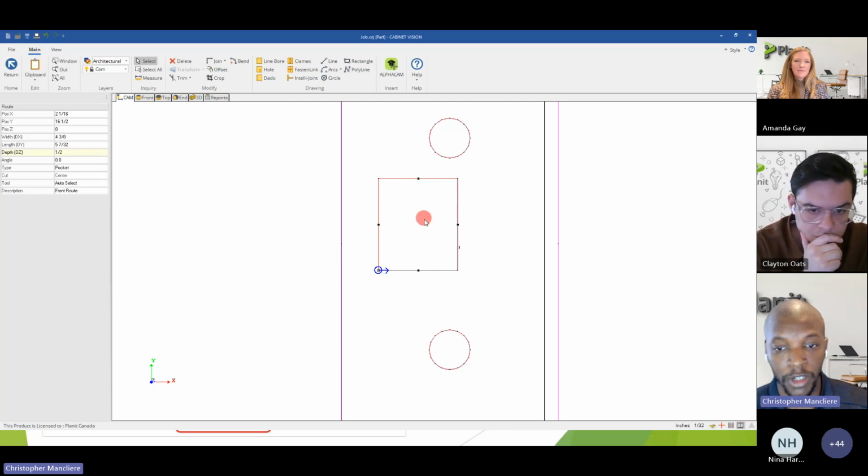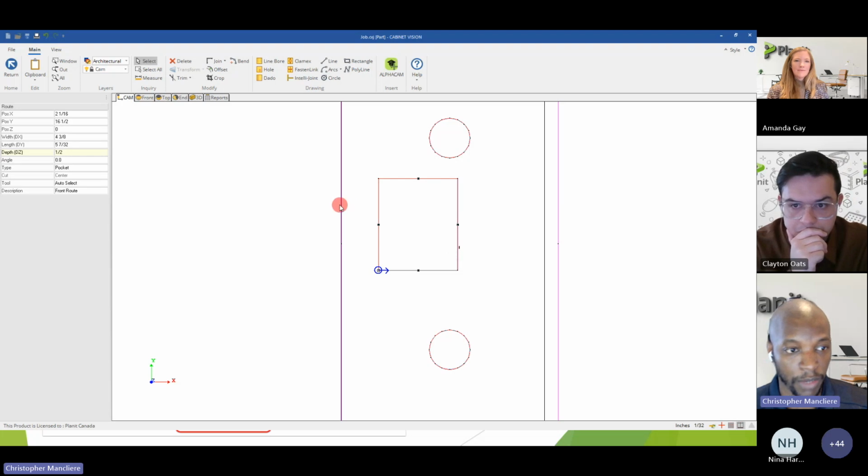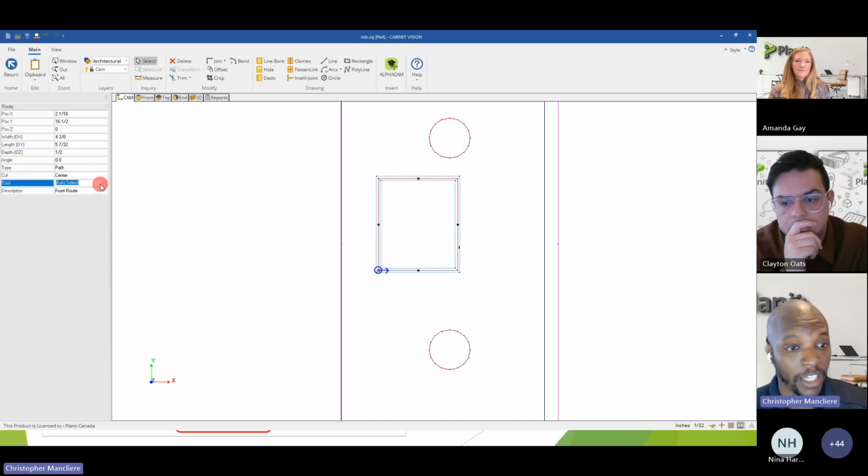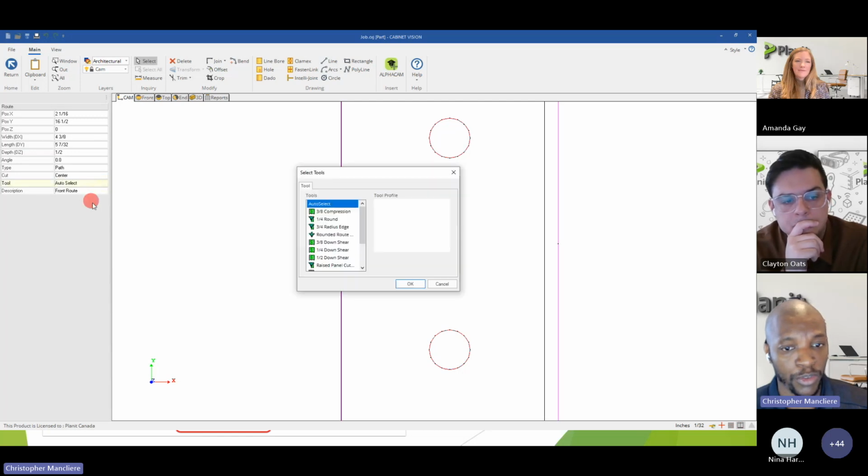So you will start in the middle and then clear all the material until you reach the boundary of the geometry you have here. So this is with pocket, and if I switch back to path, I can have, again, my tool conversation. And also you can assign a tool. So assigning a tool will allow you to select a specific tool to do an operation.